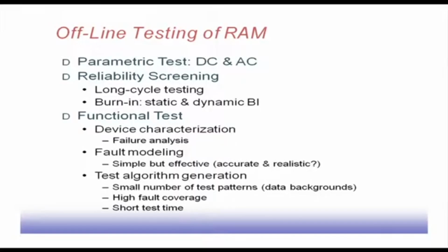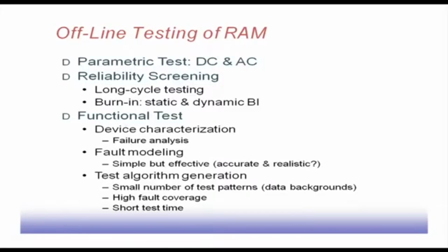Then burn-in. This can be static or dynamic burn-in. Dynamic means it is put into system operation, and static means it is statically tested, before putting it into the functional test. We do some testing so that we get some confidence about its operation.